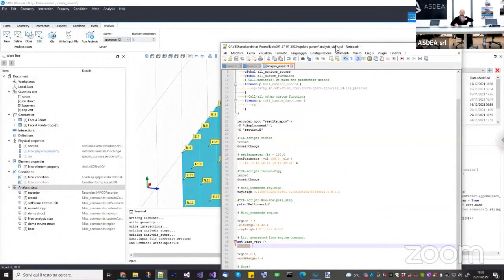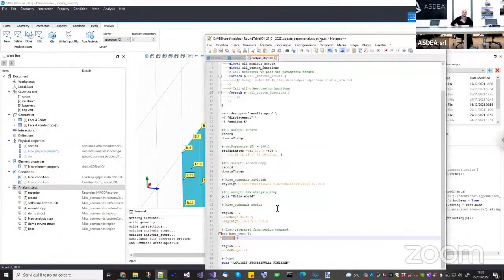Okay, now we are running out of time, but I want to explain how it works. Because if you have this list here, you do the same for the other vertices, for example the top vertices. Then you can add a custom Tcl script that does a loop between the base vertices and the top vertices, and you can create connections between them. It will be quite complicated, but if you are interested in doing that, you can write on the forum, and we can help you doing this.